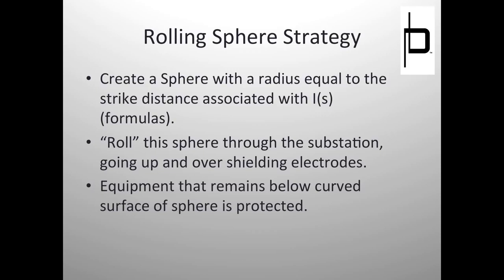And the reason we go up and over it is because the surface of the sphere represents all the items that are within reach of that step leader. Right? If the center of the sphere represents the step leader, then the surface of the sphere represents all the items within reach, or the limit of the reach of that step leader. Right. Does that make sense?